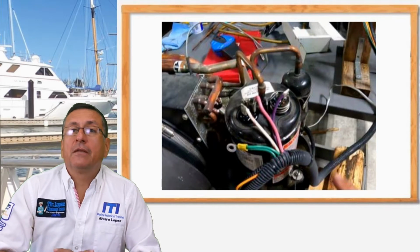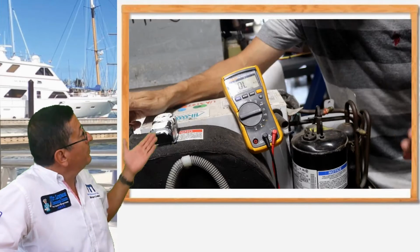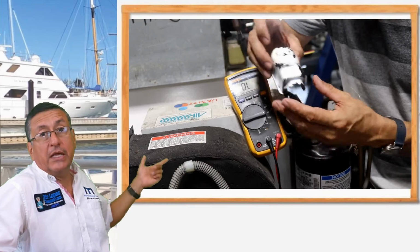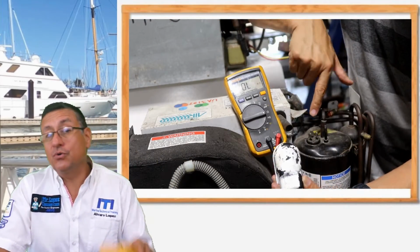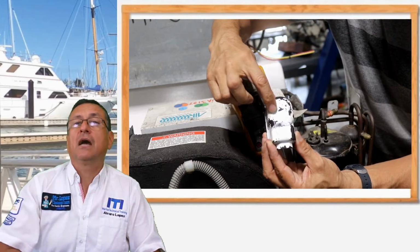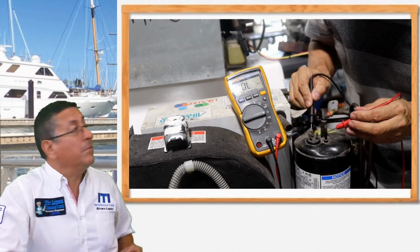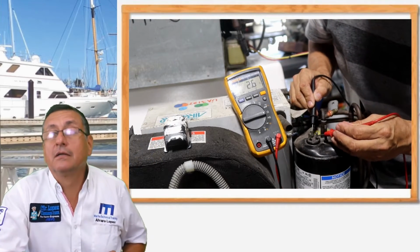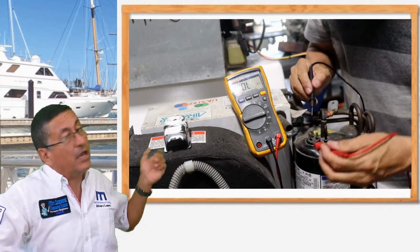The second element is the star relay or motor relay. You remember I explained in a previous episode that the relay has three terminals: common, star, and run. And we are going to use the same multimeter in ohms with no power on the system, and we are going to check the readings. The first one is the reading in between common and star. We are going to copy that number. For example, this is 800.